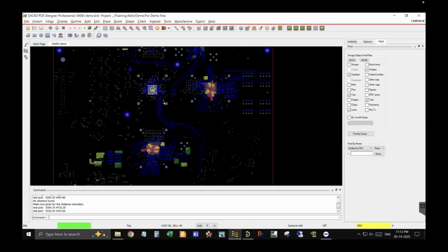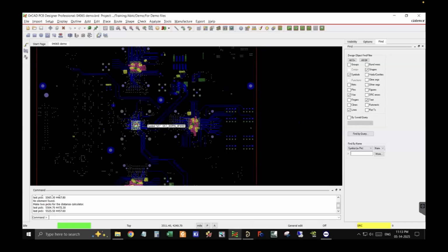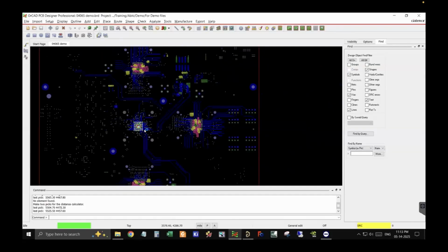Now, these ICs we do not know. So what are these? These are just the sockets. As you can see, these are holes. So only the sockets were given to us, and all the connections were known to us. On this particular board, there were some 70 ohm impedance traces which had to be routed from this particular BGA to all the 3 BGAs over here. There were 3 different sets of 3 different colors, so they were going over here, and over here, and each set had to be length matched with a length of not more than 2,100 mils, which was approximately 5 centimeters. That was the limitation, and it was told to us that we have to do that.